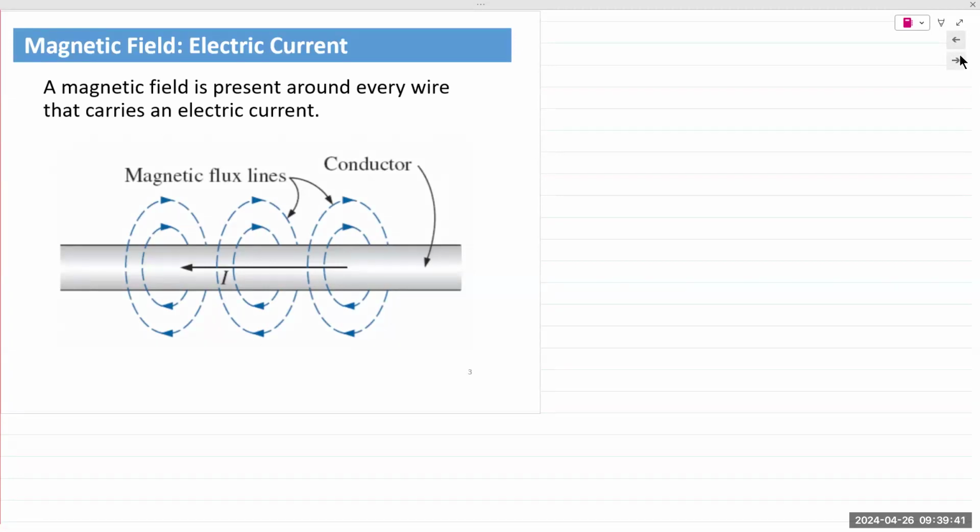Its job is to carry 120 volts from the power outlet to the adapter. So, 6 feet long, resistance is there, it's very small. Maybe it's measurable, maybe it's not. But the level of the resistance will not interfere with its job of supplying 120 volts. Similarly, it has inductance, it also has capacitance, but the level does not rise to the level of interference.